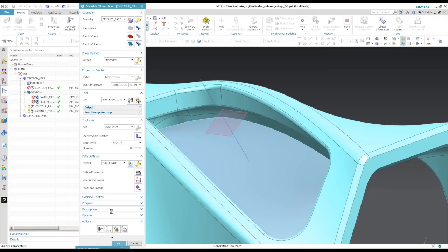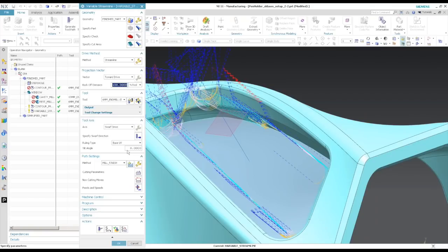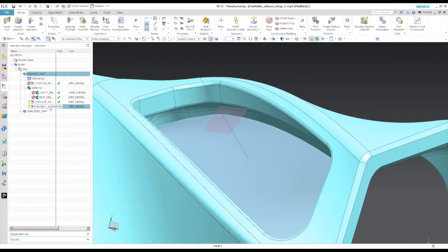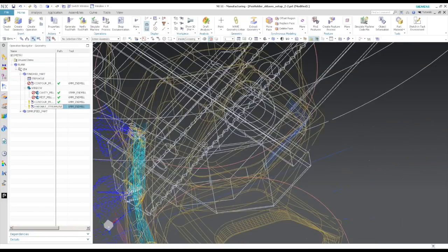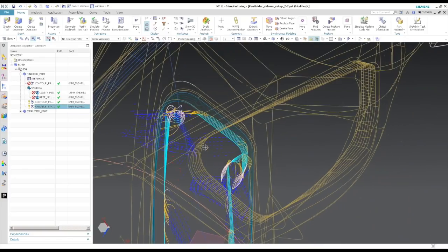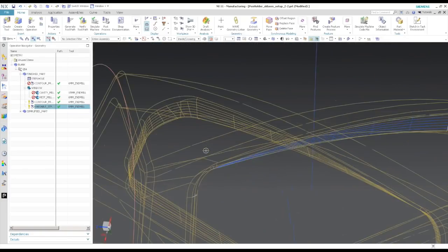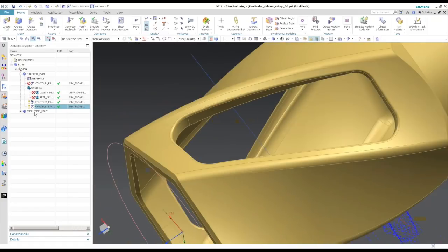So Siemens is basically giving you two methods. NX is trying to give you two options there, with the base UV and the swarf, in case you do have bad model data. So here's looking at the swarf, but if we copy this, let me check which one I had smoothed out here. So I believe it's that one there. Okay, so we'll copy that over.